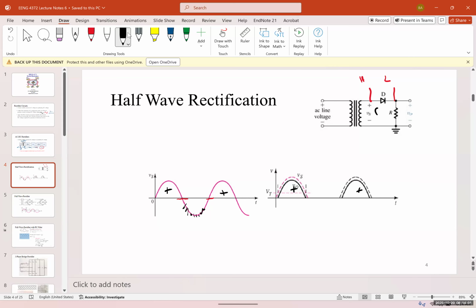You can only pass the current in one direction. You can't pass the current in the opposite direction. It doesn't go that way. Therefore, you're going to be left with half of the signal. When you put it on low, it will connect the other side of the diode, or the output of the diode, and therefore you can have half of the energy delivered to the system. And the speed and the temperature drop when you have half of it.